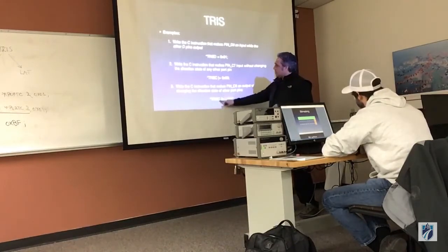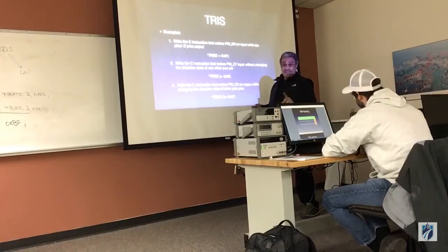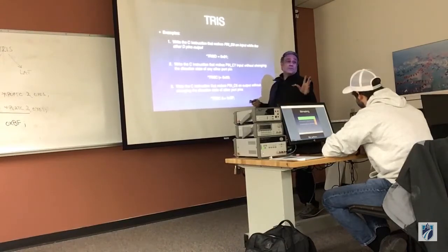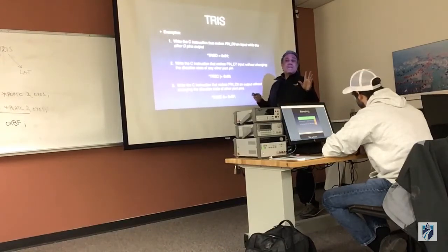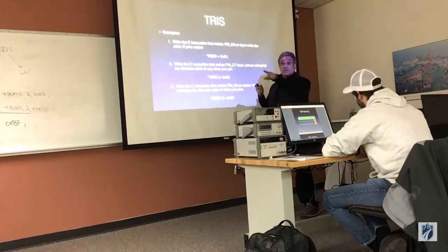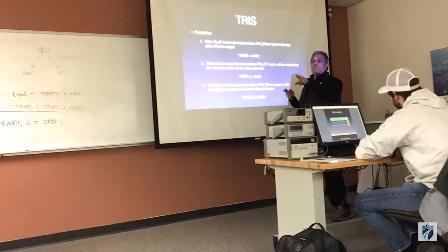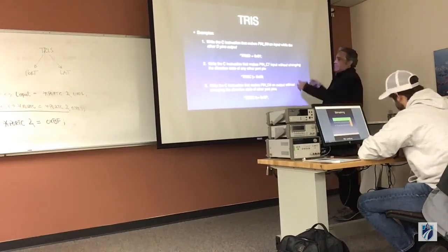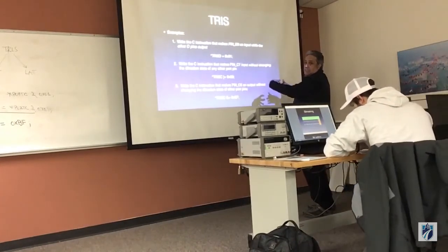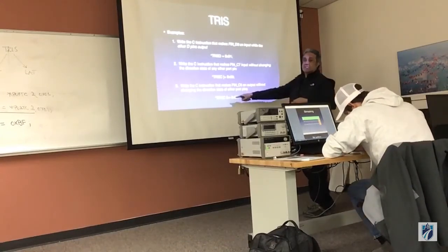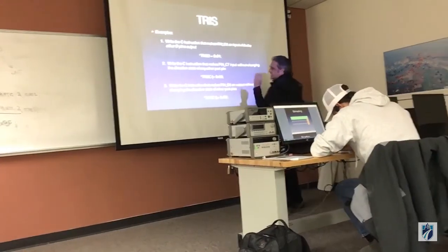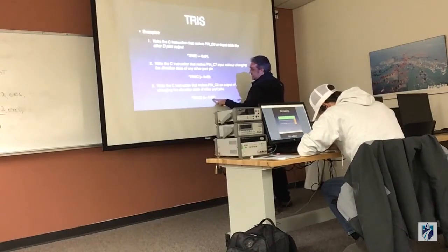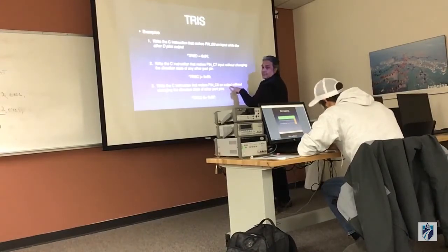But notice that the operation is exactly the same as the 5 volt or the 0 volt operation. But the behavior is different because we did it on a different circuit. TRIS C and port C are not homogeneous with each other. Why? Because a 0 on position 6 makes it an output.